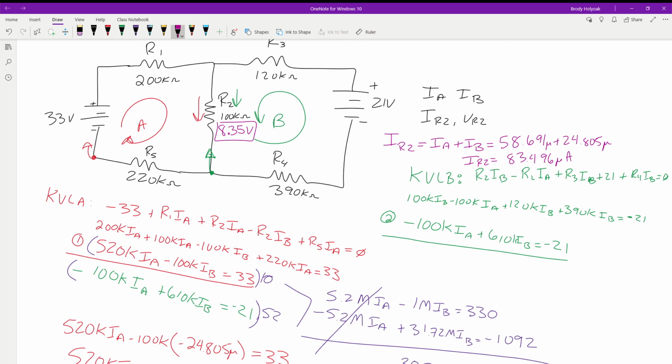The current will all get taken care of itself. We build circuits to adjust all those. But as we're going through, we're like, okay, we have 100 volts to start with. We're dropping 10 from here, 10 from here, we're dropping 15 from here, we're dropping 25 from here. And so across this guy, we should have this much. Well, when you go in to measure them, you can quickly see how much does each of these systems have. Well, all of a sudden, one of these systems is taking 30 volts instead of 15 volts. So that's when you go in and you either try to calibrate it or you have to replace the module.